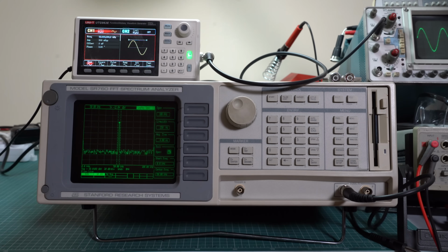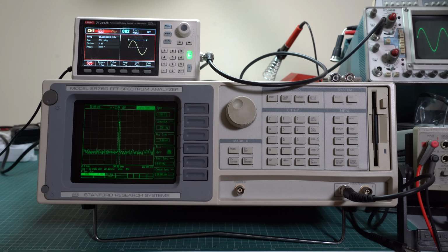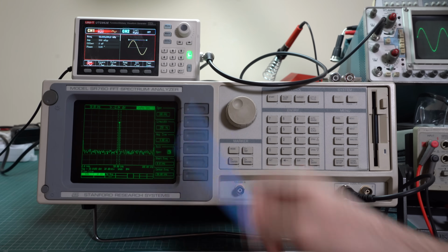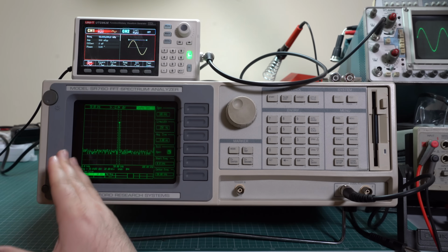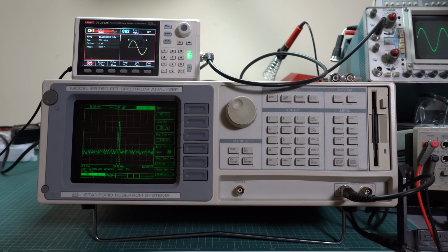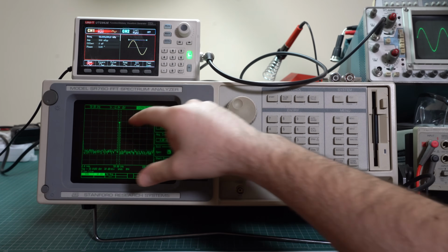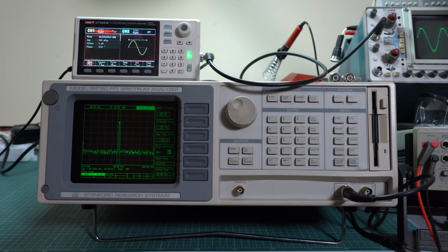Another set of important settings is the way you configure the axes. That's because on a spectrum analyzer, the graph that you have on the screen is usually a double log graph, meaning that both the x-axis and the y-axis are logarithmic. This is an interesting trick that we usually do in RF because this allows us to see detail in both very low frequencies and very high frequencies. And this applies of course to the y-axis, where this allows us to see detail at very low amplitudes and also have a signal that is much higher in amplitude visible on the same screen, as you can see right here. So to demonstrate this really quickly, we can change the settings just a bit.